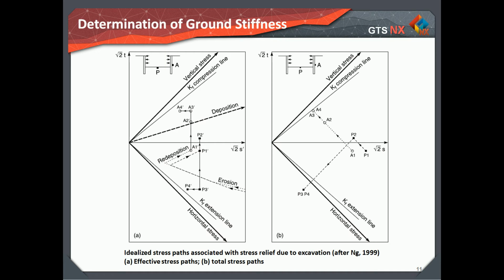The S-shaped curve shows that for strains in the typical range encountered in retaining walls, conventional triaxial test results are not applicable. This is because of bedding type errors associated with measuring displacement in conventional triaxial cells. Special triaxial equipment with local transducers mounted on the specimens is necessary. If stiffness values at strains lower than about 0.001% strain are required, then data from equipment such as the resonant column or bender elements are needed.